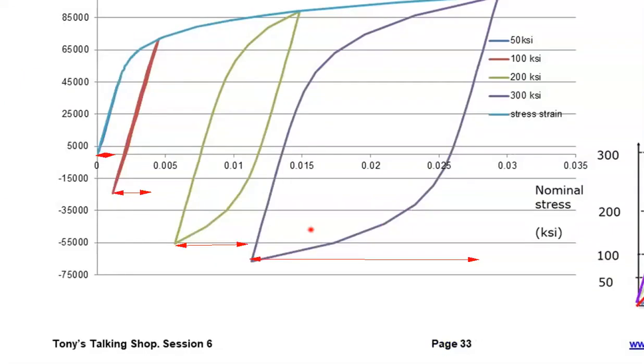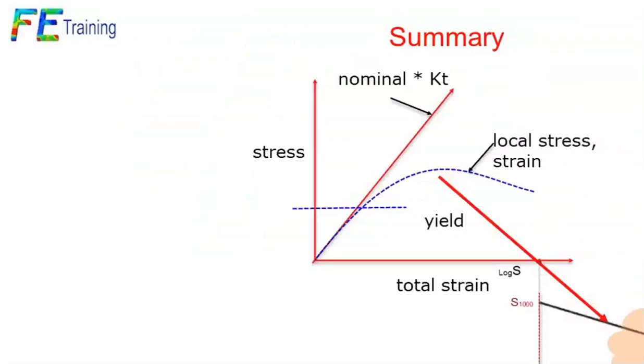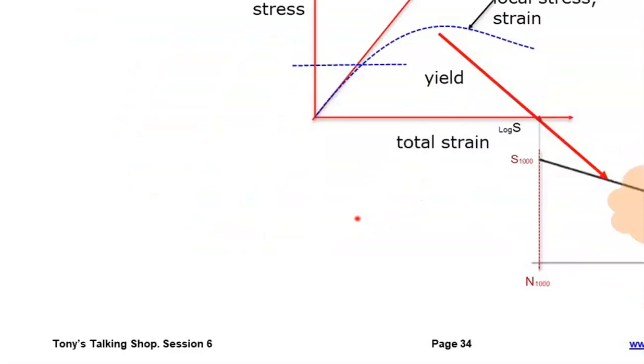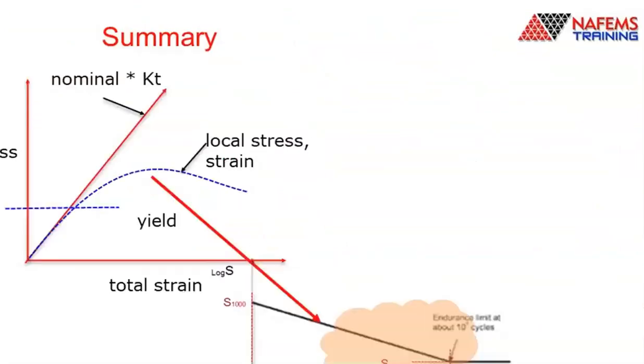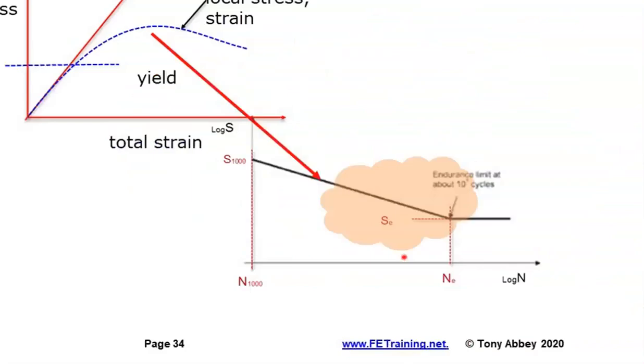And I think I've nearly finished. Dave will be relieved to hear. And this is really like the summary sheet. If we're using the SN curve approach, down in here we're okay because we're operating up this part of the curve. So the linear assumption we make for the peak stress is okay.